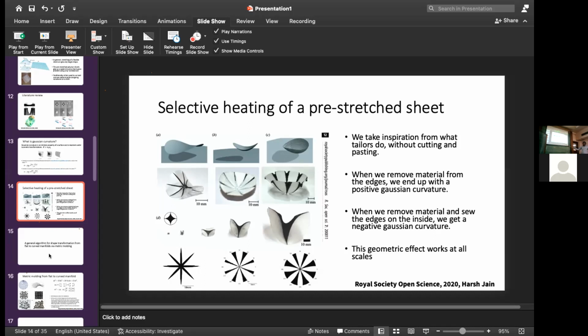That's what I'm doing in this egg shape, right? I'm causing it to contract more in this part and less in the upper part. The only way to make it contract more is to actually draw larger patterns. So the entire thing with the same amount of heat, you can't fine tune. I cannot control the heat per se. It could be done, but I have not chosen to do that. I've chosen to only control the pattern.